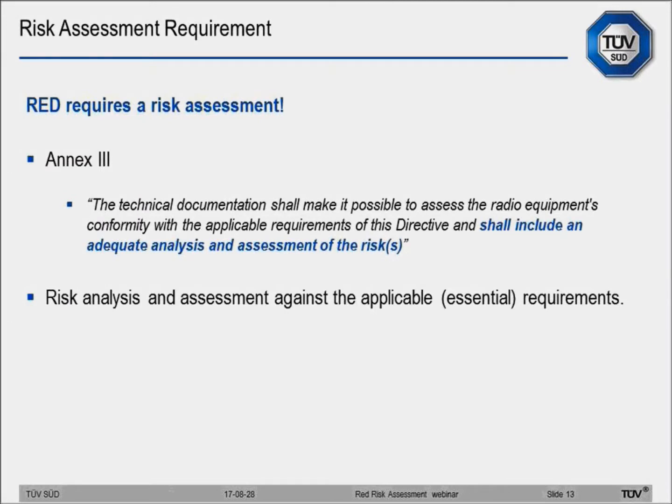In all cases, the RED requires a risk assessment in the technical documentation. A key point is that the RED requires an analysis and assessment of risks. In other words, a risk assessment is required. Throughout the RED, the theme of risk relates to the essential requirements. For most products under the RED, essential requirements of health and safety, EMC and spectrum use always apply. And therefore, the intention is to ensure compliant levels of risk with the essential requirements.